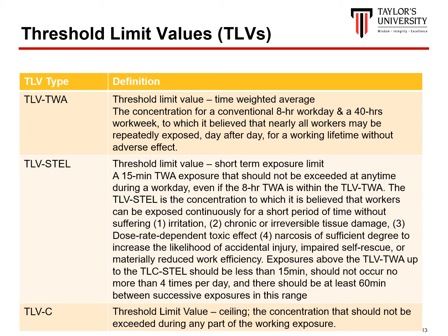The second level of exposure limit is what we call the STEL, the short-term exposure limit, where remember we have a 15-minute exposure and a 1-hour gap and another 15-minute exposure, and at maximum they can only be exposed up to 60 minutes a day within this exposure limit. And there's the third level, which is what we call the ceiling value, where if the concentration exceeds this, no workers are allowed to be in the workplace until we bring down the level.